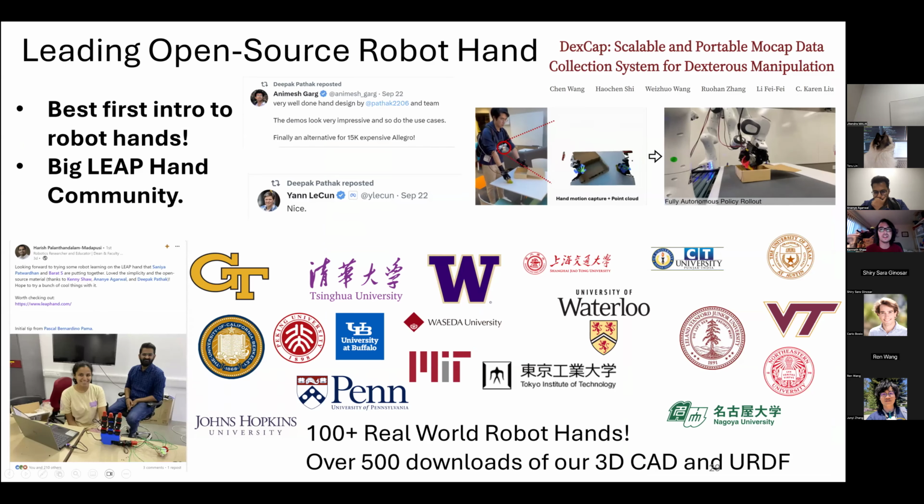So one of our first attempts at this was looking at the tendon-driven design. There's many robot hands out there, and we tried to make our own. So you can see on the bottom left, there's 3 different tendons pulling on different parts of the finger, and these fingers are 3D printed really easily. And there's a bunch of control that I won't go into, but how you tension these tendons and how you control them to know where the fingertip is actually quite difficult. And you can see on the top right, the nice thing about hands like this, when they're soft, is that you can bounce them on the table and they don't break. This is a real concern with robot hands with all these different little joints that can be often fragile.